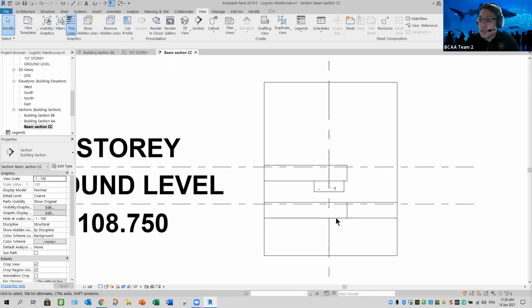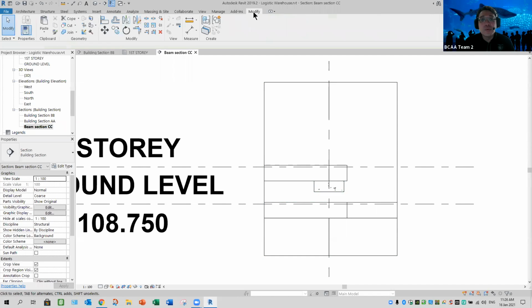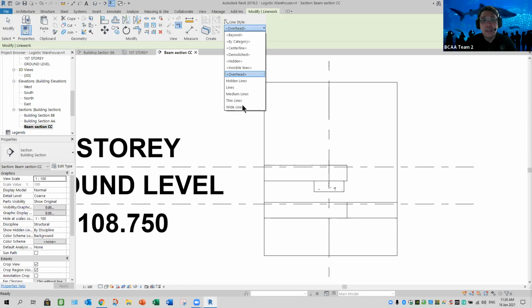Now, although you cut them as a section, only this view is 2D. Whatever your model displays in 3D, some lines that are overlapping can still be hidden. That means if you go to modify tools, you are still able to hide some lines, like invisible line, don't show, overlapping.